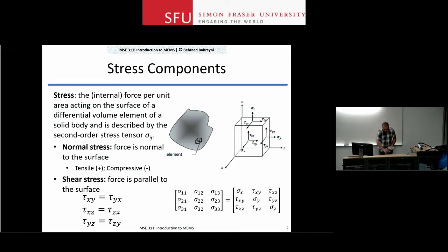By basically, so on tau xy, you can find it on this graph as, let me bring up my pointer. Tau xy is shown here. This is the component of stress. It is acting in the y direction, on a face that is normal to the x direction. And sigma x, or sigma xx, the normal stress, is here, right? This is my x-axis, normal stress, the force and the deformations are along the same axis.